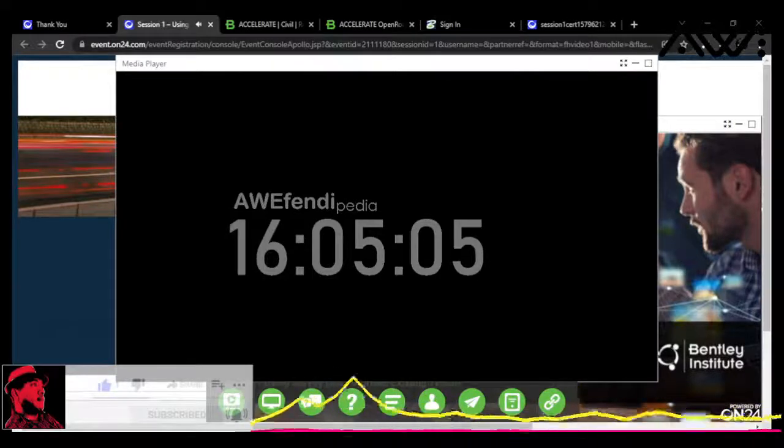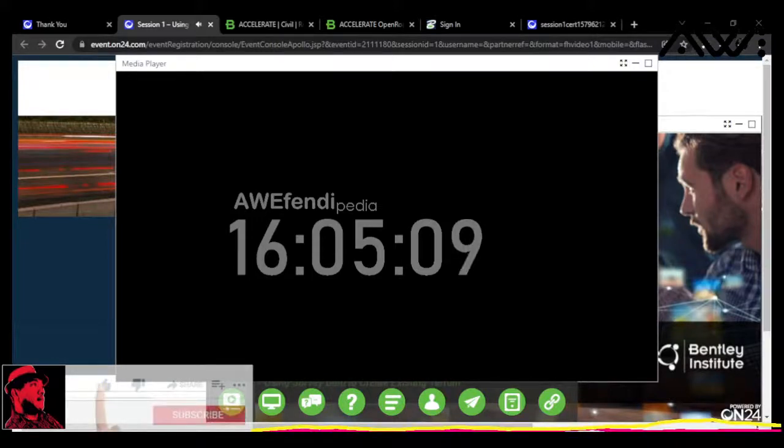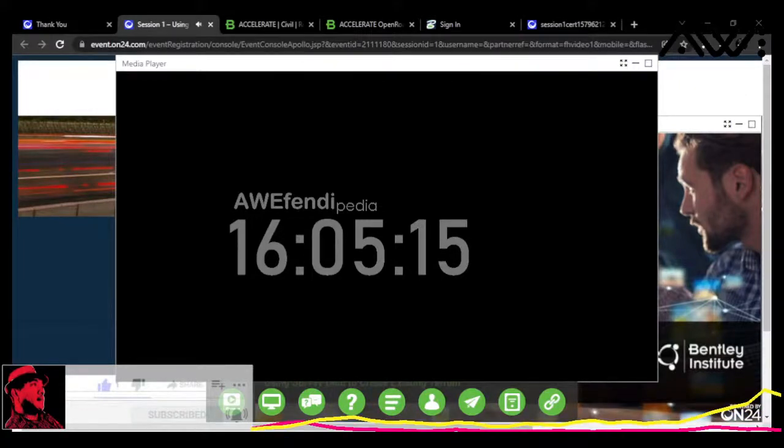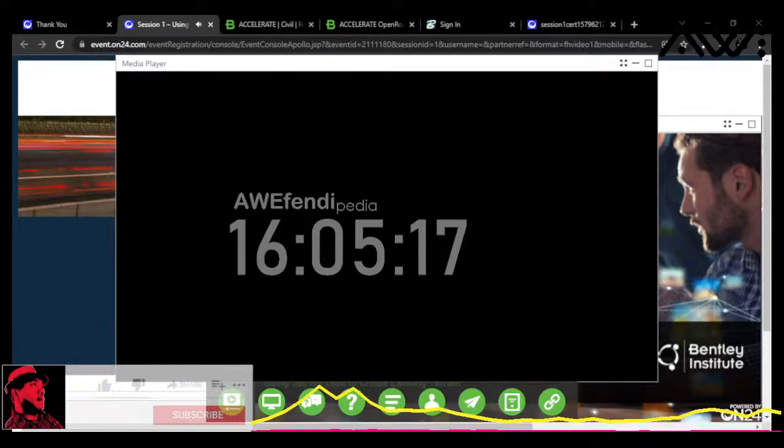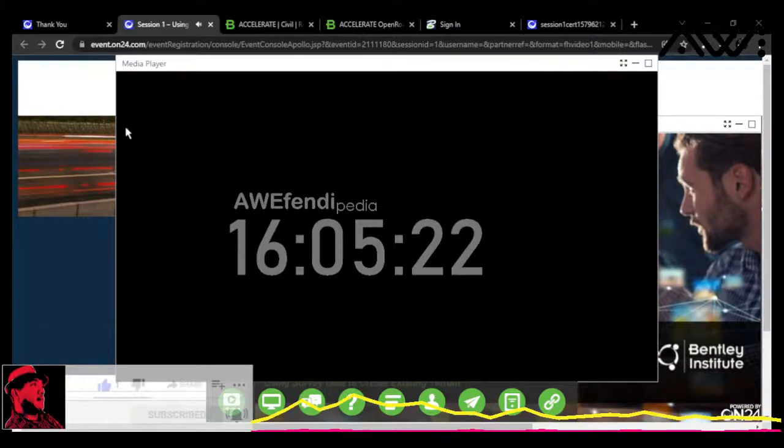This time I'm going to choose about half of this first round, so we're going to choose files 2 through 11 and import those, and we'll say open. When we hit open, it's going to go through again. It's going to match the alpha codes with the feature definition. It's going to look at the link codes and string all those together.